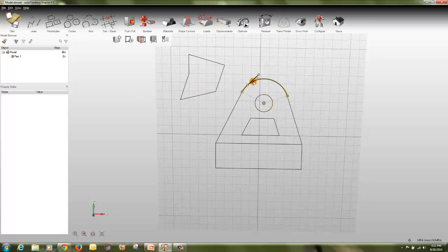So in this way you can apply the sketch constraints on Inspire. We will have one more circle here, one more here. So this and this concentric. So this will become concentric. So you have to just, again I will show you how you can do it.